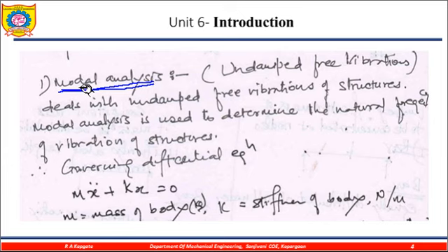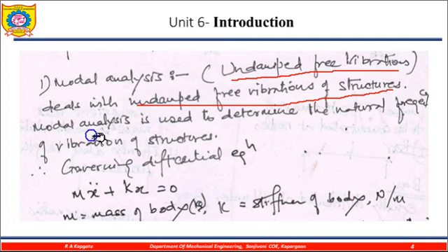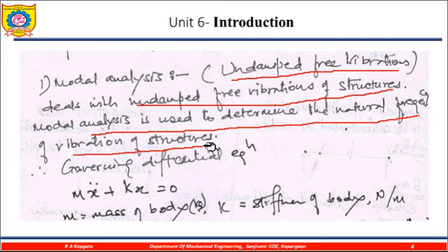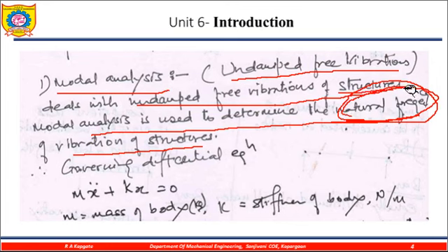So let us know what is meant by modal analysis first of all. What is modal analysis? Modal analysis is undamped free vibration, or it deals with the undamped free vibrations of the structure. Modal analysis is used to determine the natural frequency of vibration of structures. So it indicates the natural frequency. Because of modal analysis, you would be able to find out the natural frequency of a structure that is going through undamped free vibrations.